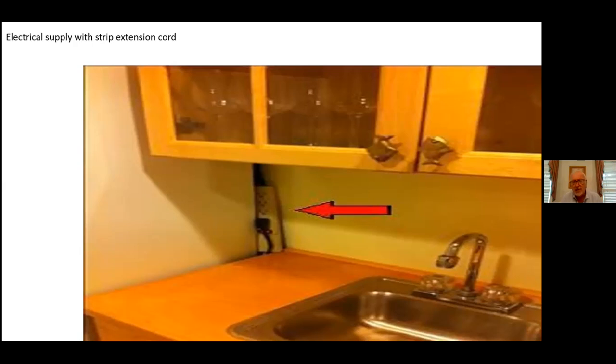I guess the reason why they did that was because it would be tough to pull out that refrigerator and reset that button if it did trip. There also might be a water line connection back here for the ice maker, perhaps, or water dispenser. It would have been a better idea to have the GFI, or even just a regular dedicated electrical outlet, behind the refrigerator and a GFCI out here somewhere closer to the sink.